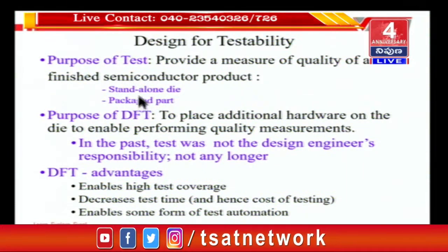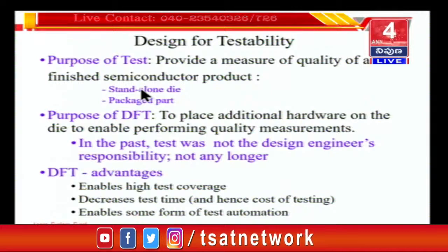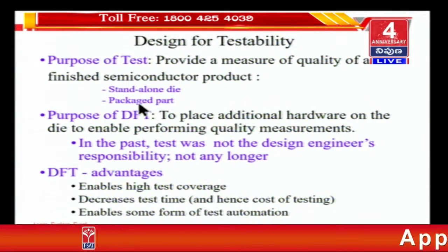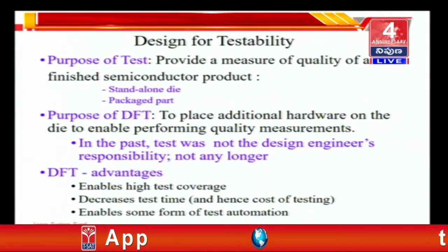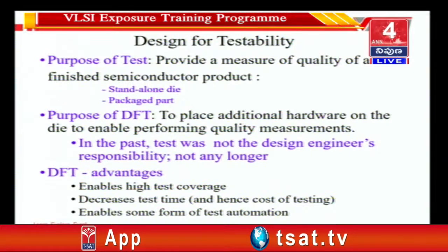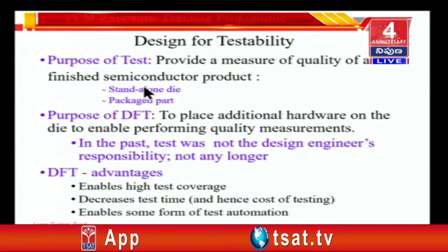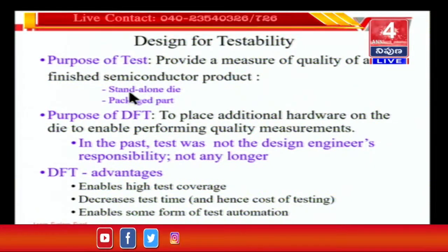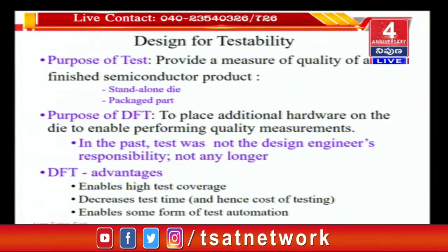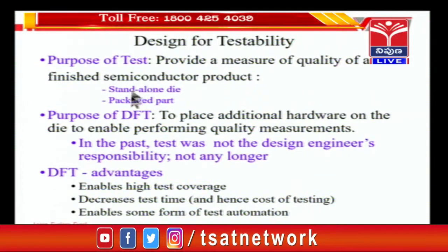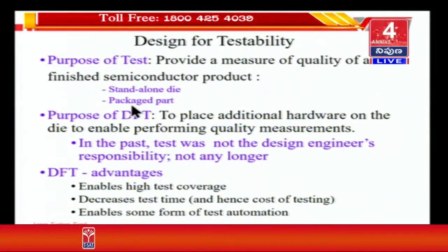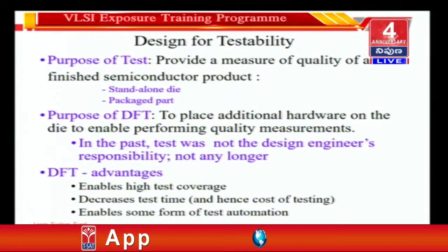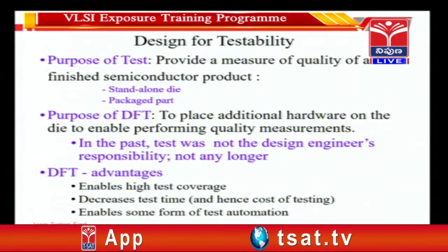Packaging happens only after testing. 100% testing is done for VLSI chips immediately after manufacturing, and only the good parts are sent for packaging, and after packaging, on a sample basis, some of the chips may get tested.